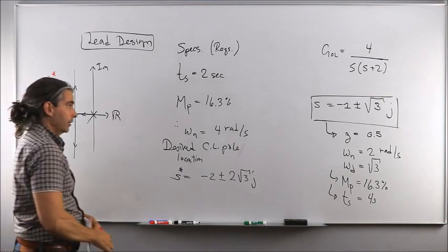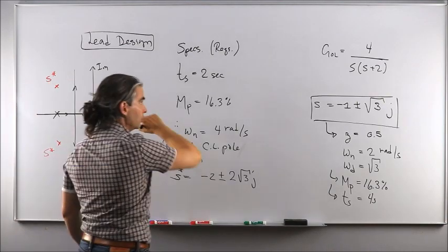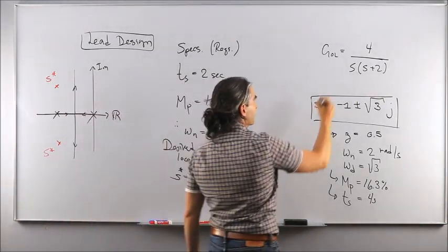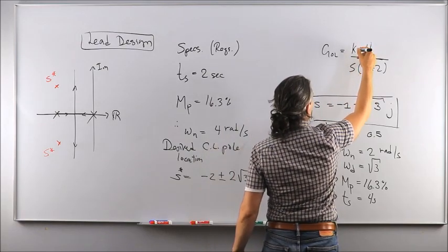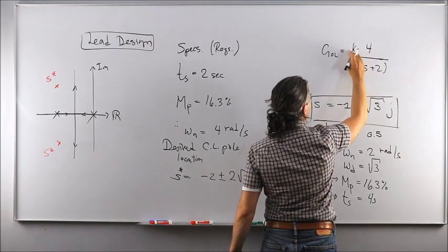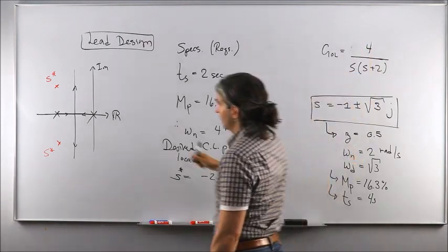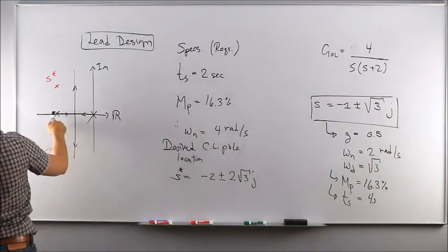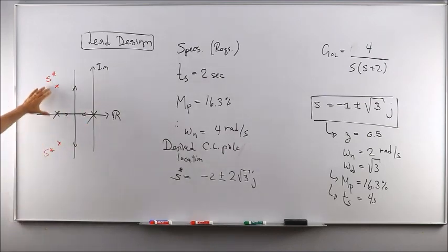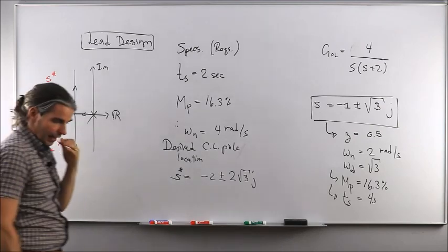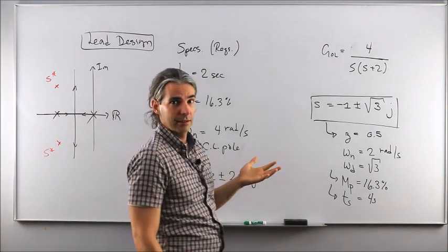Well, currently, if I were to just increase the open loop static gain, if I just take that and multiply it with k, and let k vary between 0 and infinity, I'm going to get this map for the closed loop poles, right? So they'll never go through the desired pole locations indicated in red in this complex plane. Is that a problem? Well, yes.